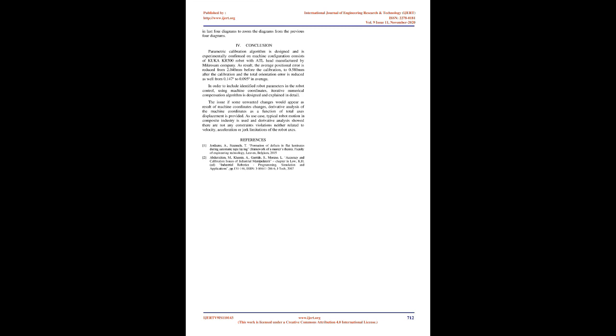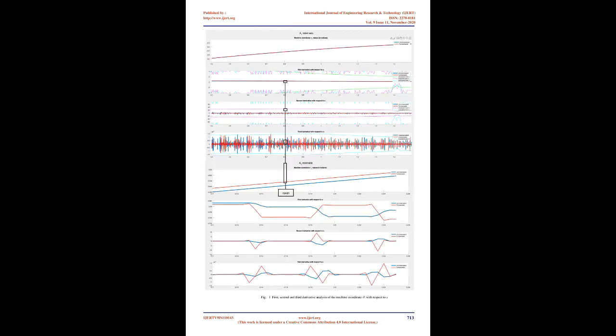Even more, feed, acceleration and jerk constraints for each machine configuration axis are expressed with respect to total vector displacement s, allowing trajectory planning, optimizing the feed, and allowing a simple analysis of whether there are any constraint violations before trajectory planning is done. More details on how such constraints could be derived are given by Altintas and Erkorkmaz 16.